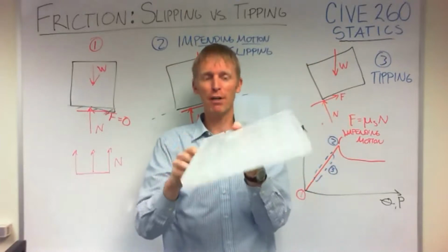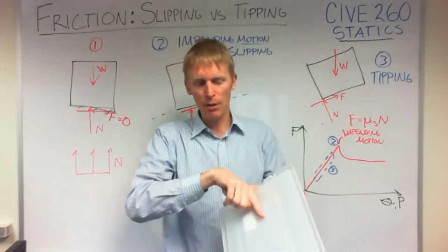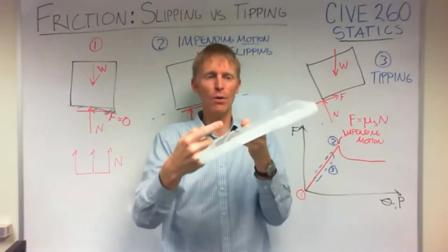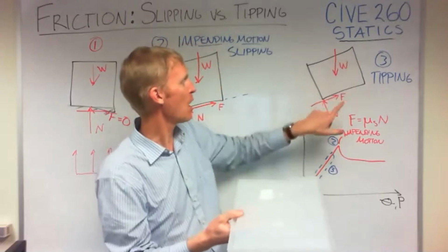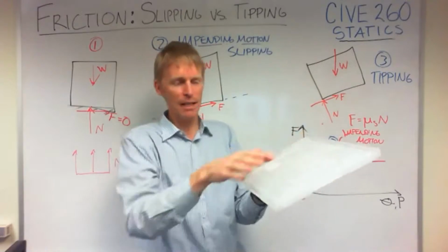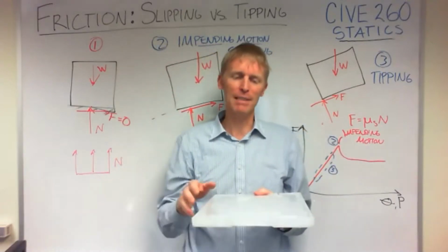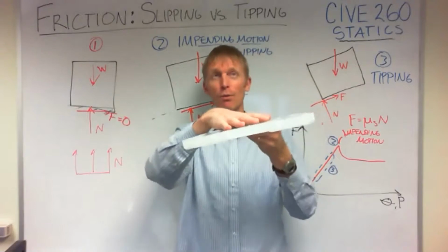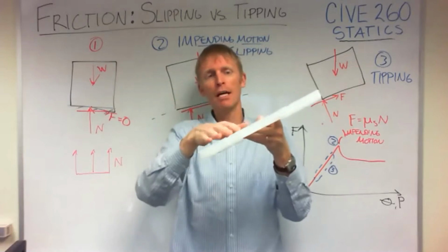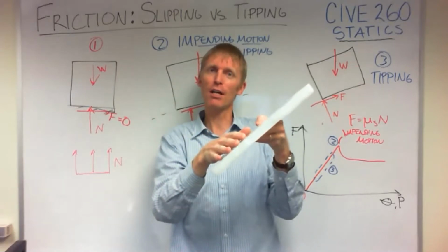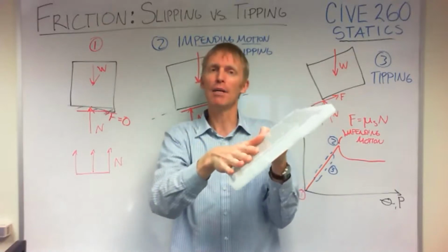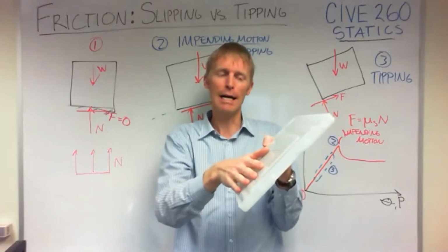And it turns out there's two different frictions. There's one friction if you wanted to speed up or slow down your car, but another friction that comes on the side of your tires. And so essentially you can think of this as the front of your car, this being the normal force, this being a friction force holding your car up that slant. And so that'd be another basic design consideration where we want a certain amount of superelevation to make it more comfortable coming through this curve, but you actually don't want to make it too steep, because then if you had a car coming through that was going very slow, it actually could slide down that curve if the surface conditions were slick.